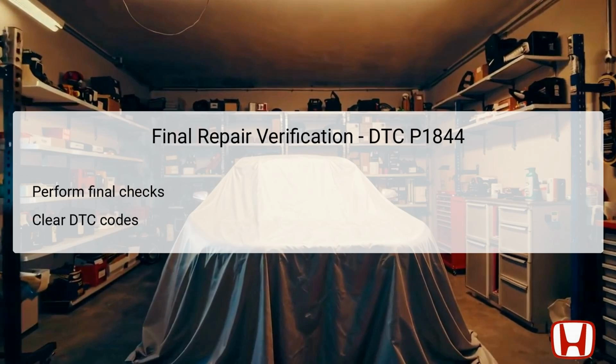Once the DTCs are erased, conduct a test drive to evaluate the overall performance of the transmission and verify that there are no lingering concerns. It's essential to confirm that the shift position indicator operates normally and does not exhibit any irregularities afterward, ensuring that all systems are functioning as intended. This verification phase is a critical step to guarantee the success of the diagnostic and repair process.